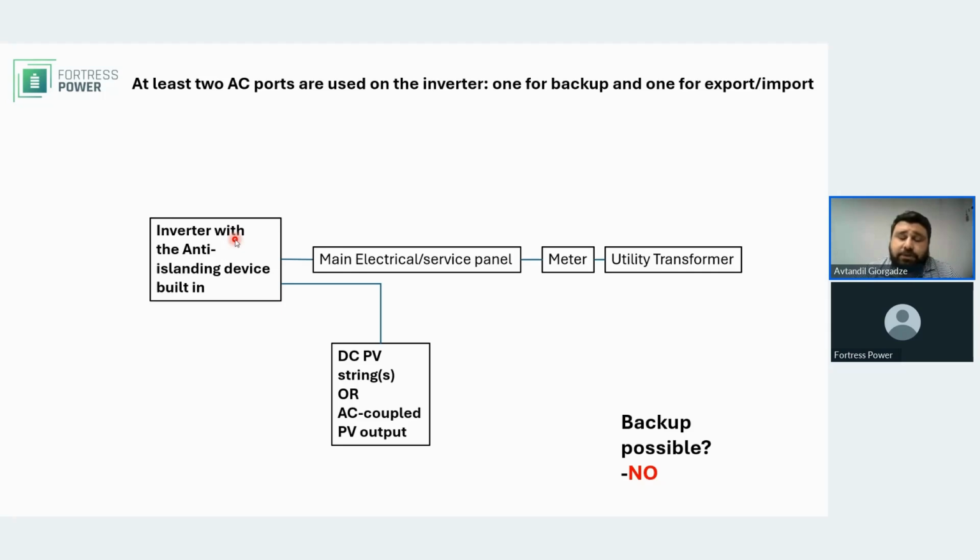In the majority of cases, the line side tap allows you to have more power from your energy storage system than the load side tap. Because think about it. If it's the load side tap, you have one source as grid, the other source as the ESS. And those two can generate together way more current flow than what the electrical panel bus bars can withstand. And you cannot change those bus bars, because that would require you changing the entire thing.